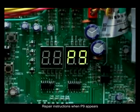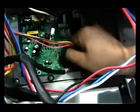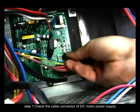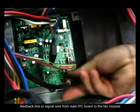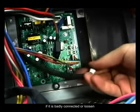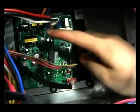Repair instructions when P9 appears. Step 1. Check the cable connector of the DC motor power supply, feedback line or signal wire from the main PC board to the fan module. Check if it is badly connected or loosened. If it is normal, please go to the next step.